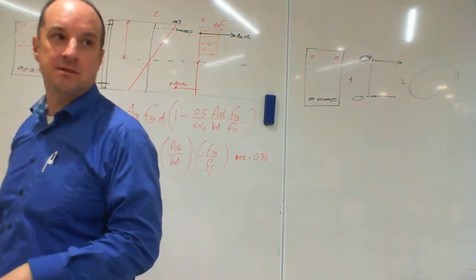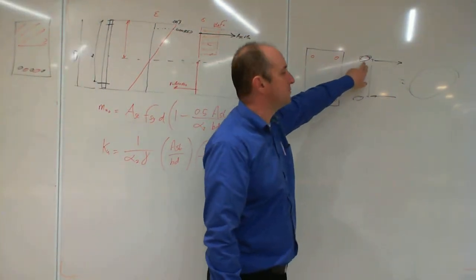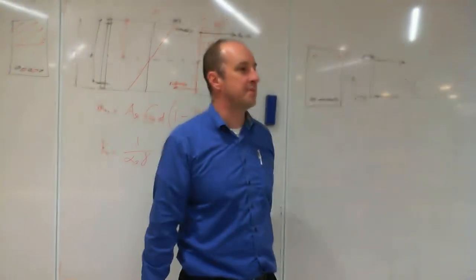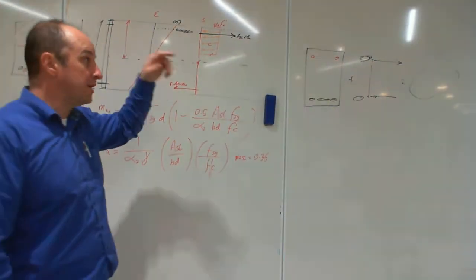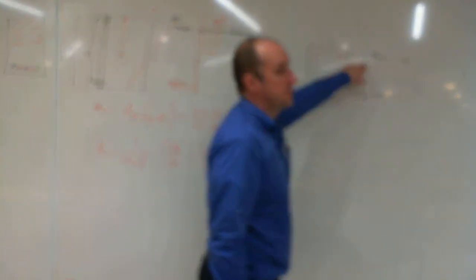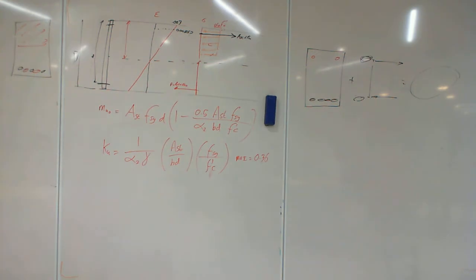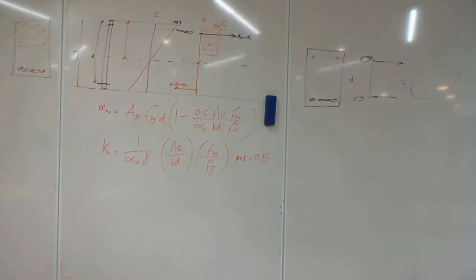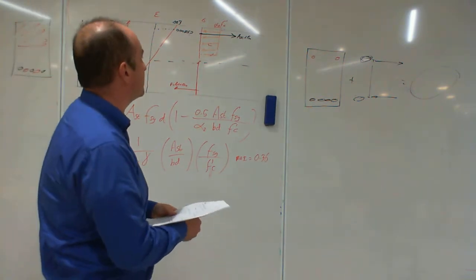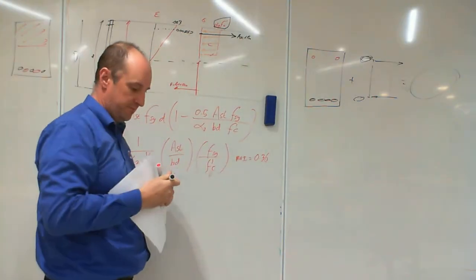Does that make sense? Because we can't use the force twice. So we're saying, yeah, whatever that force is, whatever that stress is, we're taking 32 megapascals of stress away from it. Okay? The maximum that could have been was 500. If it was 32 MPa concrete, 500 minus 32 is 468. Okay? Now, when I said the F-C, it's actually not the F-C, it's the alpha 2 F-C, that value. Okay?